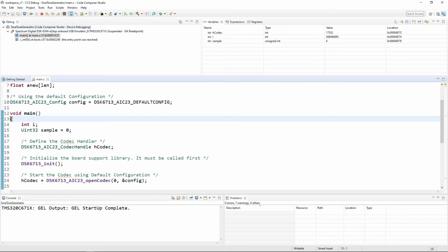That machine code has already been programmed to our DSP processor. But after the programming, it is now waiting for the instruction from Code Composer Studio to start its execution. As soon as I press this resume button, our code will start running on our DSK. It means in our case, as soon as I press this button, I should start hearing an audio sound, rather a sine tone.